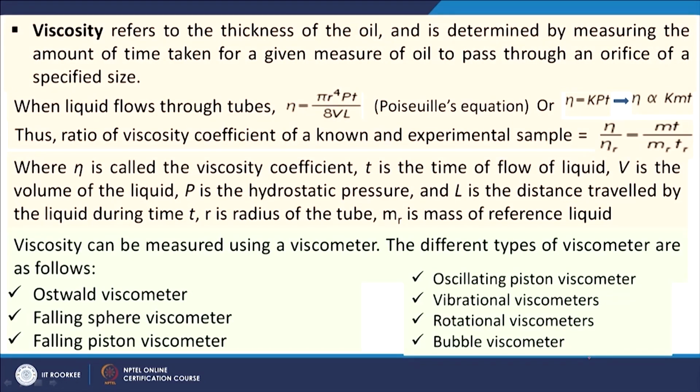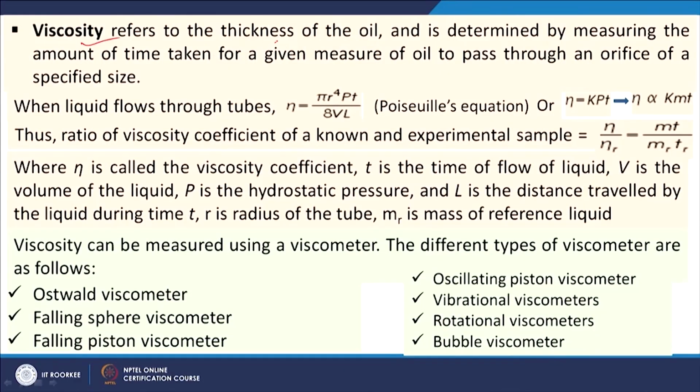Viscosity is another property of the crude oil which is very important for its transportation and for pumping purposes. As you know, viscosity indicates the resistance experienced when one fluid layer flows on the other layer, and that is related to viscosity. It also refers to the thickness of the oil and is determined by measuring the amount of time taken for a given measure of oil to pass through an orifice of the specified size.